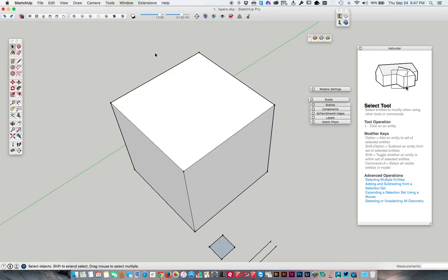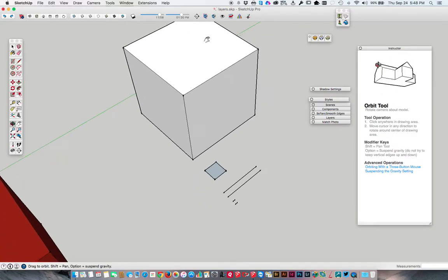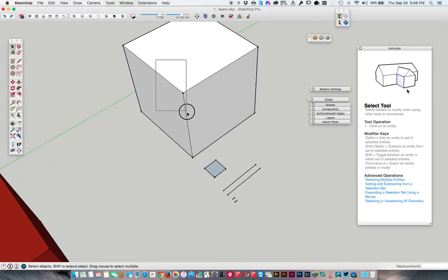Another way that you can add is to simply drag little marquees, just like the little animation was showing here. See, if you go from left to right or right to left, it shows you different little windows. So if I go left to right, starting up here, I click and hold down, and I'm going left to right, and then I let go. It doesn't look like it's selected anything. Actually, let me show you in here. Let's go from left to right, and I'll do this, and it's a solid window. You can see there's a little solid lined window, and when I release, it has selected one thing.